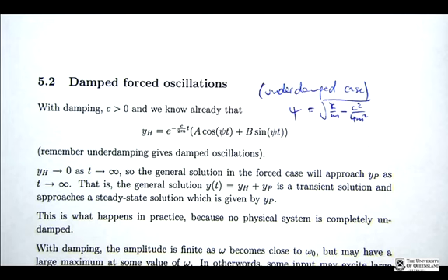And this is only in the case of underdamping, right? If it was an overdamped system where the damping was very high, you can imagine this if we put our spring in a jar of honey or something and, say, pull it down and release it with some initial condition. You can imagine that the object would not have decaying oscillations, but it might just slowly retract back to equilibrium and not oscillate. So honey might be a nice example of an overdamped system, but I'm only going to be considering underdamping in this case.